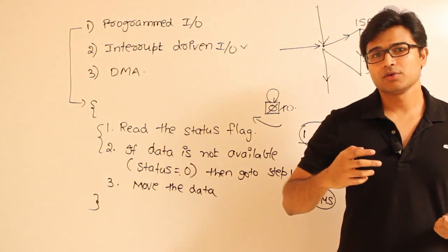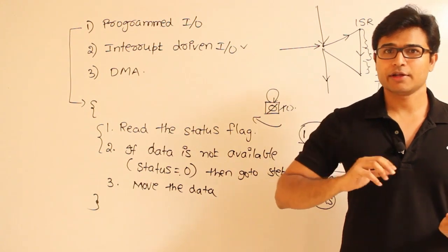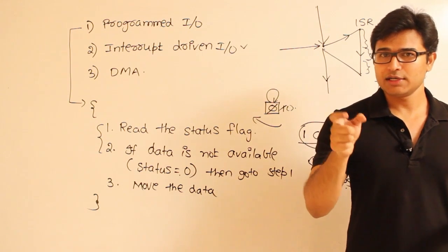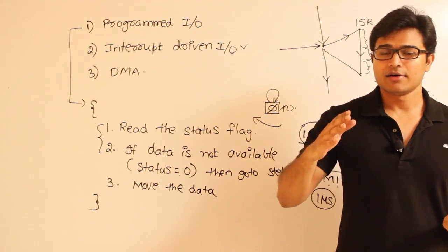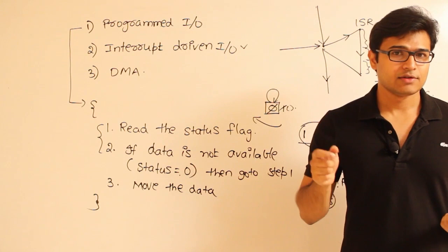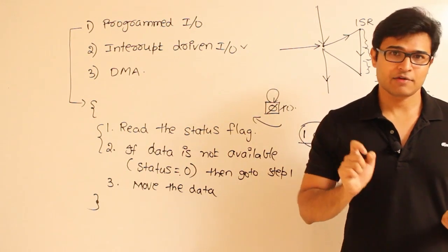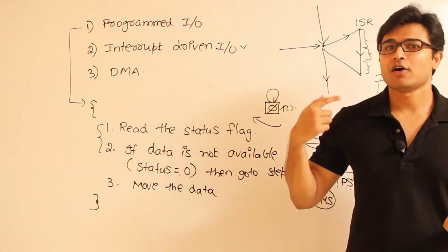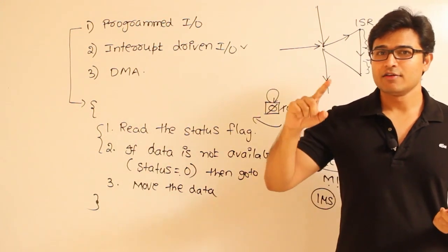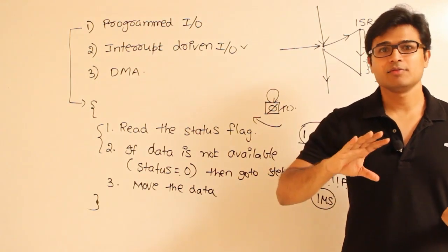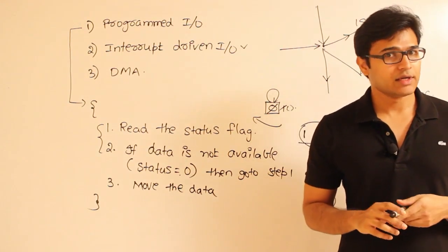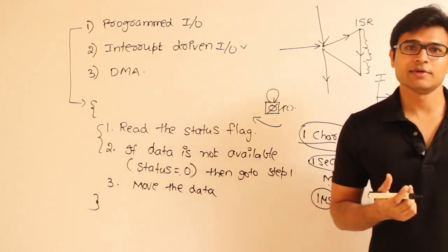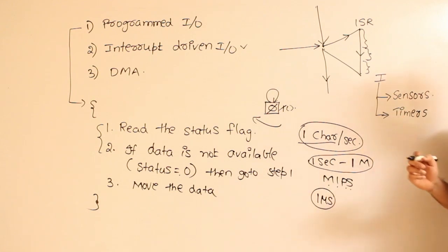So you don't want to have a particular program run forever. We want to allocate it some time slot, and once the time slot is over, we want to schedule the next process, right? So for that reason we are going to have a timer, and whenever a program is executing, our timer will give a hardware signal, and that signal will lead to context switching and then the process switching, right? So it also has to be given the highest priority. Generally the second highest priority will be given to these sensors and then timers, right?